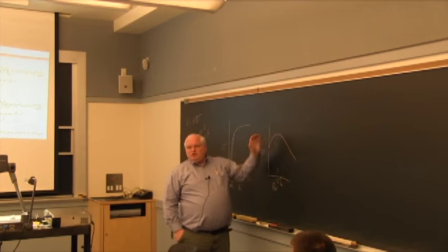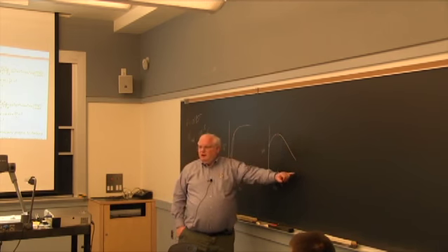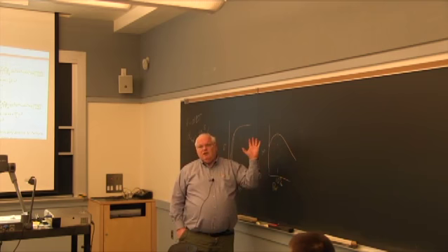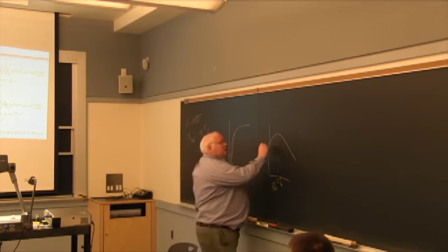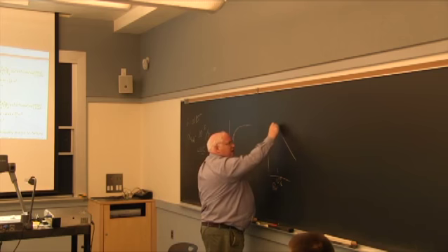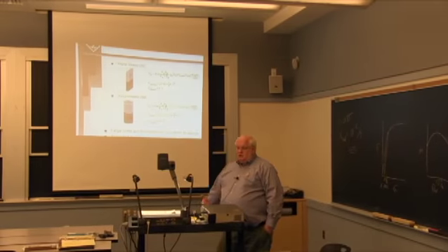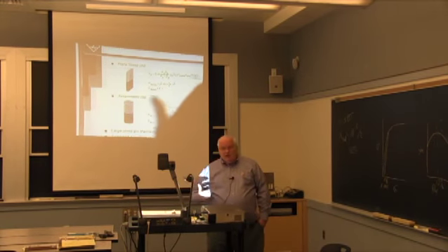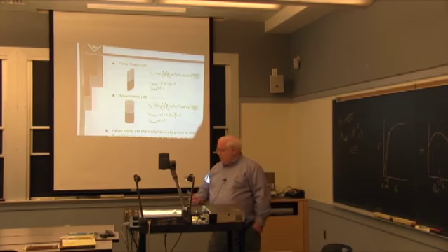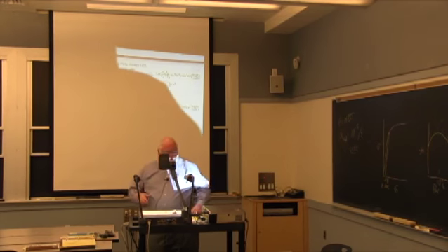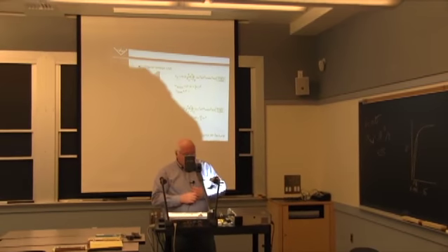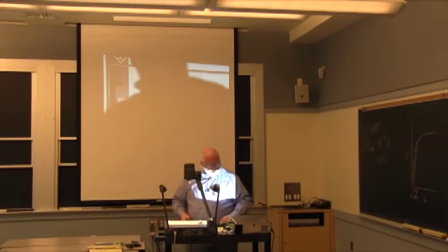If you had some porosity, sure, you're losing bonded area and you've got stress concentrators and everything else, but you actually first increase, and somewhere around 10%, you start to decrease because now the amount of bonded area is so small. But initially, you're reducing residual stresses, and then you've got this competing effect of losing bonded area with porosity. So some porosity actually can be good in a dissimilar material joint in terms of combating residual stresses. But another principle of dissimilar metal joints, that's the reason I put this up.